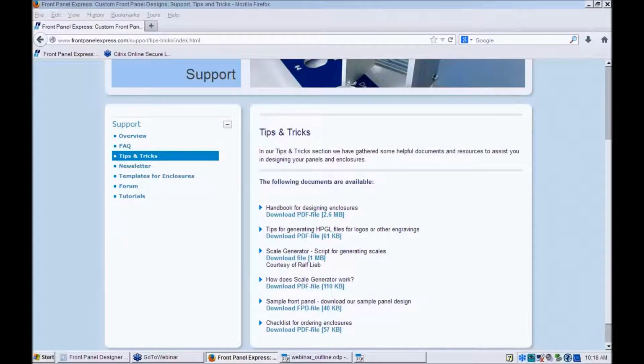Basically, a few things I can also cover is what colors and lengths Chad had mentioned. We have black and natural anodized, and the minimum length of our profiles is 1 inch and up to 48 inches. Side profiles, all of the side profiles use the assembly kit that has self-tapping screws, and housing profiles use machine screws M5.